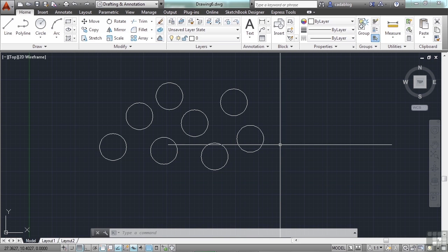There's another one called the W polygon and the C polygon methods. These create a windowed or crossing polygon. So it's kind of a hybrid of your crossing window or window selection with a fence. These methods will allow you to create a multi-sided object as your selection area instead of a box.